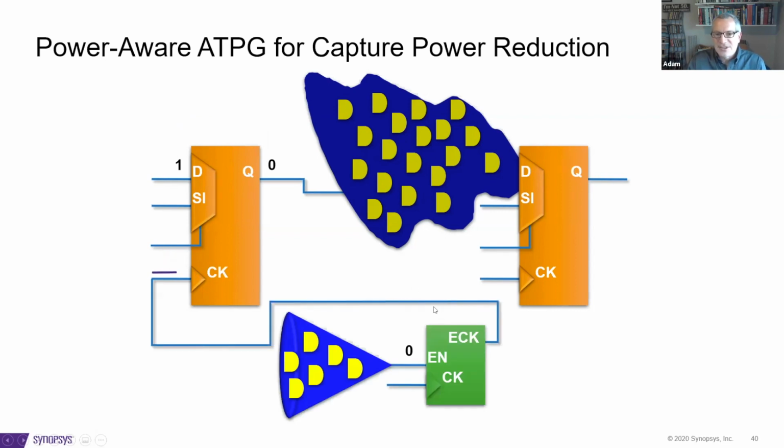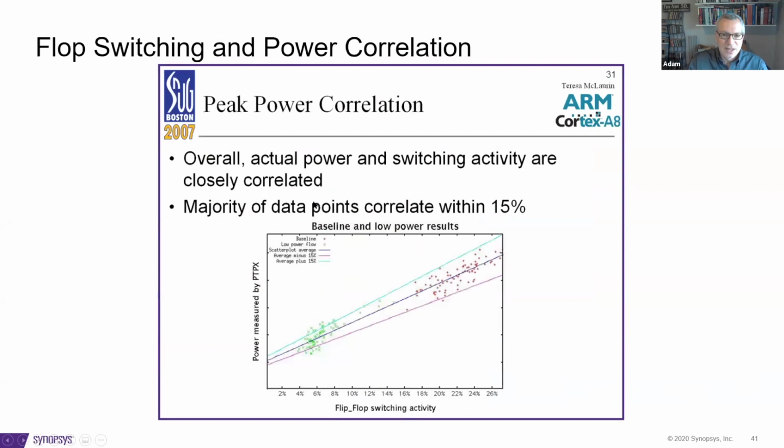So the idea here is to leverage the clock gating cell to turn off the whole tree after the clock gate, so that not only do you avoid the up to 50% wiggling of the tree in this neighborhood, but you also don't get the switching activity that happens here either. So by that token, you get a lot of reduction.